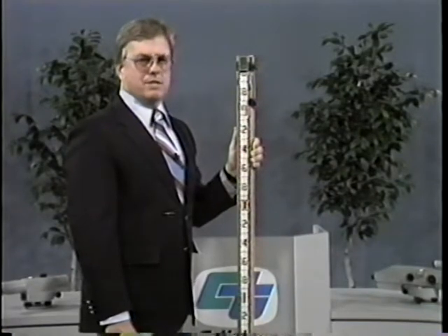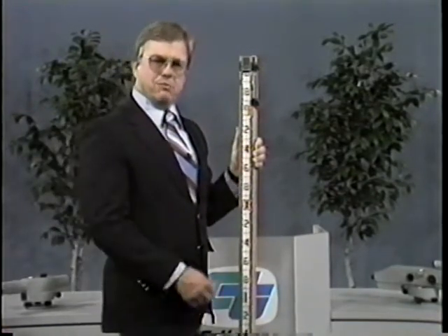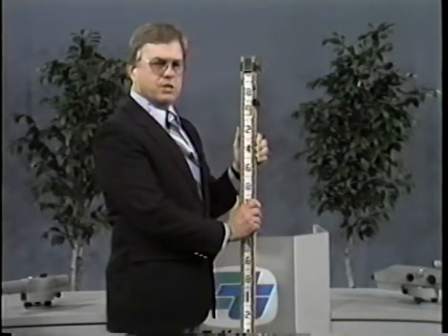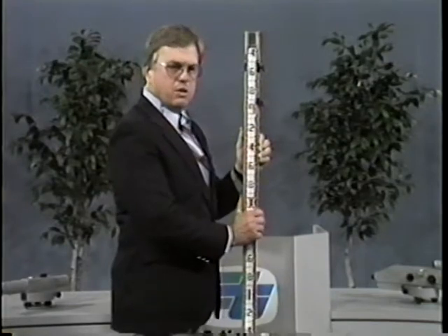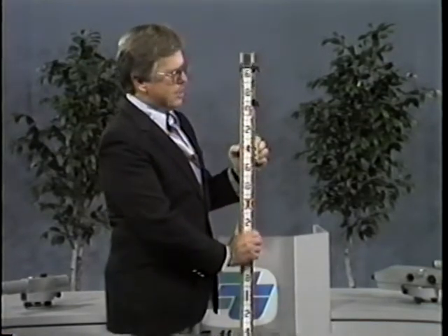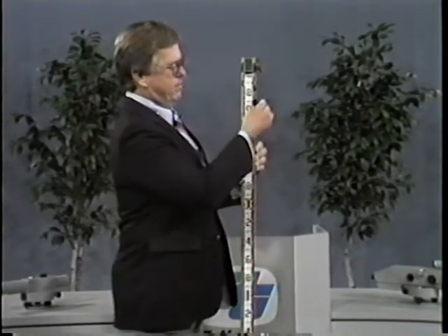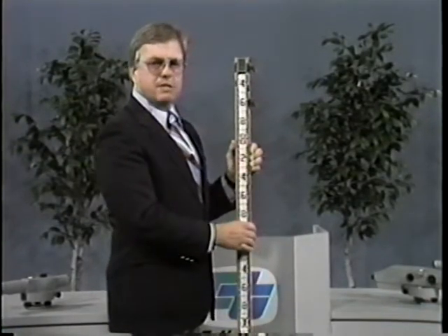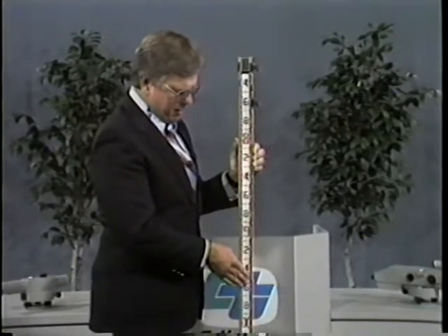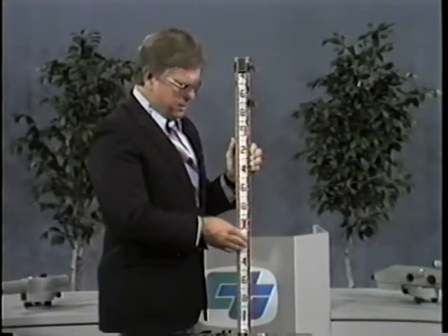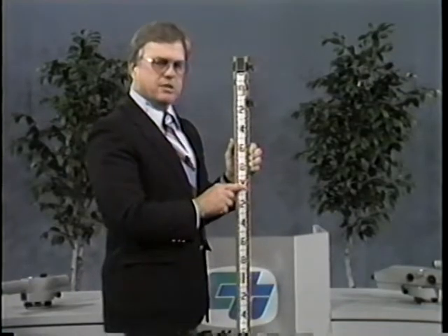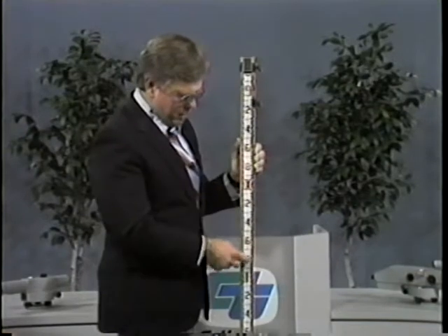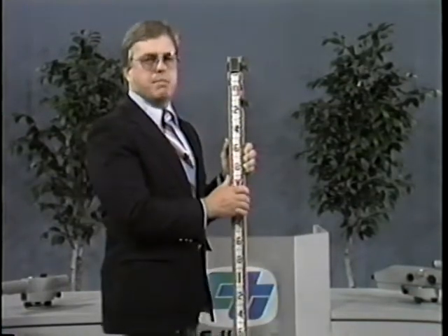This is a Lenker rod, as Carol referred to it, a direct reading rod. The interesting thing about this rod is that it's two-part construction. It has a wood section in the front that slides over the back section, and the front section has a tape that rotates around the first portion. Now, this tape is 10 feet long, and instead of reading 0 at the X and then going 1, 2, 3, 4 feet, it starts 0 at the X and goes 1, 2, 3 feet downwards, so the tape is backwards.